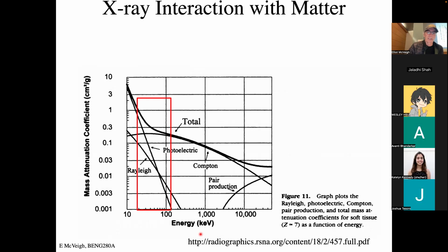If we put 10 keV photons into the sample, nothing is coming out, so your image will always be the same. You have to have enough penetration for some of the photons to survive, ideally something like 50% of them.